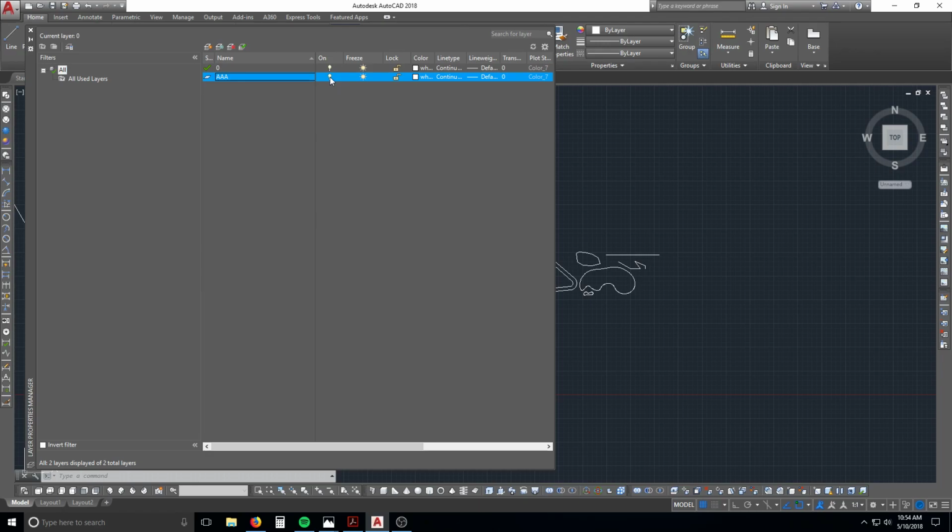But basically, if you just want to turn a layer on or off to disappear so that you can clean your drawing up, or if it's a drawing like a schematic that has, say, electrical, plumbing, architectural, dimensions, block, all these different layers, you would have one for, say, plumbing or electrical, and then dimensions overall, or subdimensions or walls or anything.